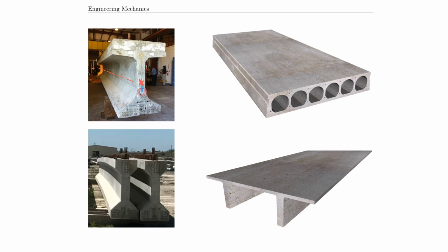And what's very important is that you have a lot of material down here that is actually removed from the centroid. I'm going to simplify this a lot right now, but this material down here is very far away from the centroid location. And the further away you move this, the stronger the beam will be against bending. And that's why you can also see very tall Florida I-beams, because they have a lot of material on the bottom, a lot of material on the top that is very far removed from the centroid. In all fairness, I need to tell you that there's also a lot of pre-stressing steel down here that is way beyond the purpose of this class. You should take classes like concrete design to learn more about that.